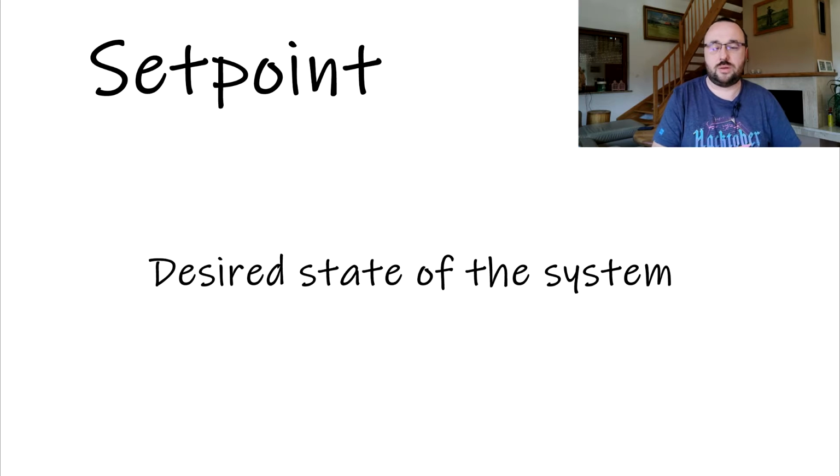In our case, RC Hobby, with the position of the stick, we are telling the multirotor drone, rotate right, for example, with a speed of 100 degrees per second, or do not rotate, stop the rotation, keep the current rotation rate at 0, and thus keep the attitude, the inclination at this given angle. That's all. This is the information. This is the user input into the whole flow of the control, in this case the PID controller.